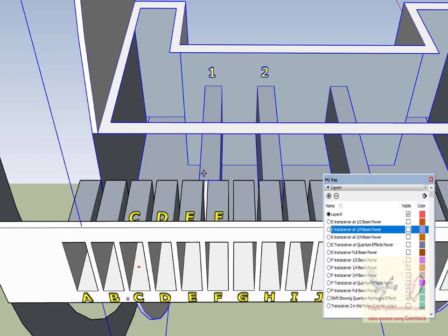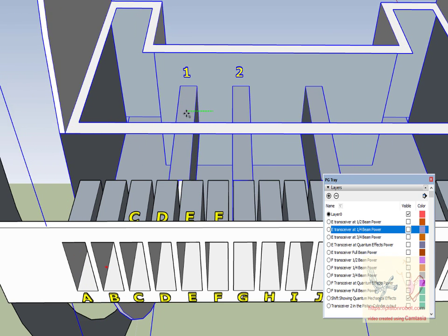So our total distance of motion for piston transceiver 1, if all we're saying is that we picked up energy at cylinder wall transceiver E, is that we are locating this to within an accuracy of plus or minus 2 millimeters, or a range of 4 millimeters, because we can say we're not picking it up with cylinder wall transceiver C or D, and we're not picking it up at cylinder wall transceiver H or I or G. So we know it's in here somewhere, but we do not know its specific position with an accuracy any greater than going from all the way over here to all the way over there.